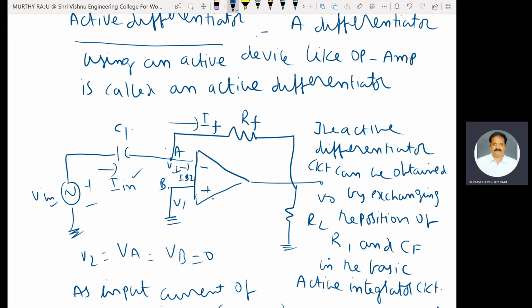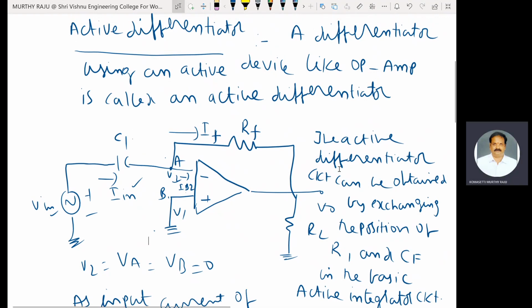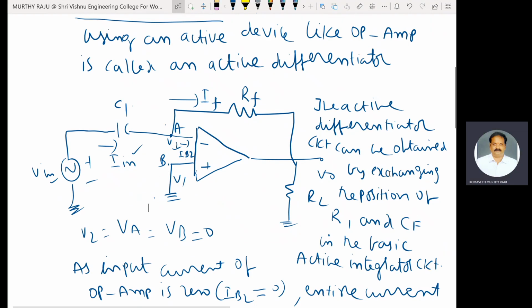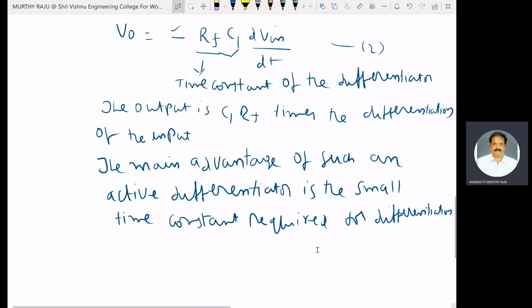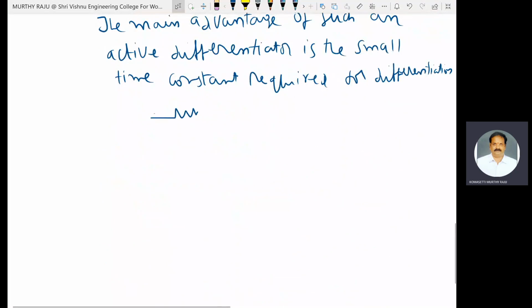According to Miller's theorem, that RF is split into two branches. One branch is connected between node A and ground. Another branch is connected between V0 and ground. By Miller's theorem, the effective resistance between node A and ground becomes... This resistance RF is connected between node VA or V2 and V0. According to Miller's theorem, the effective resistance between the input node and the ground becomes...